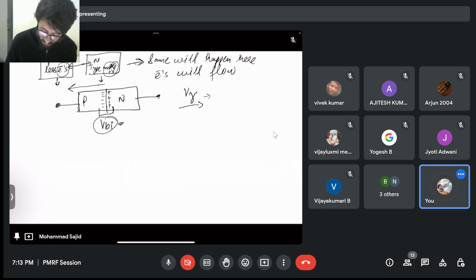Without bias, the current won't flow. This is the knee voltage, and you can understand it for the time being. The cut-in voltage you studied in the lecture is because of this. The electrons flow from N to P, and an internal electric potential develops because of the internal electron flow for a particular time, when you connect these two materials. So it is also called the built-in voltage. This was regarding the cut-in voltage.